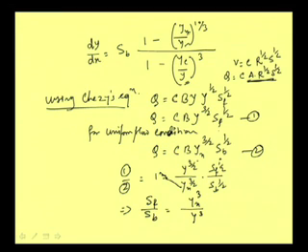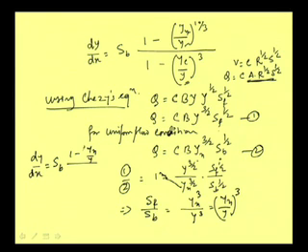And this part, yn by y whole to the power 10 by 3, we can write as yn by y whole to the power cube. Of course, 10 by 3 is nothing but nearly equal to 3 if we use Manning's equation, and using Chezy's equation we are getting it as cube directly. So, the entire expression we can simplify as dy dx is equal to SB into 1 minus yn by y whole cube divided by 1 minus yc by y whole cube.